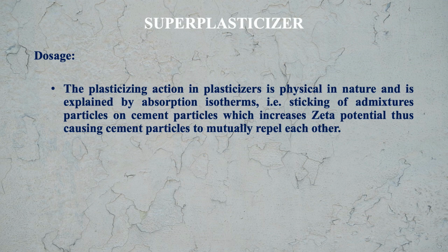The plasticizing action is physical in nature and is explained by absorption isotherms, that is, sticking of admixture particles on cement particles which increases zeta potential, thus causing cement particles to mutually repel each other.